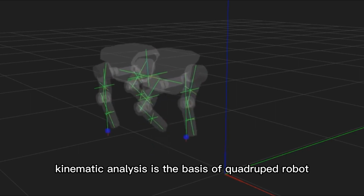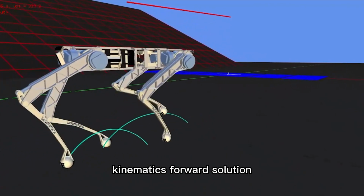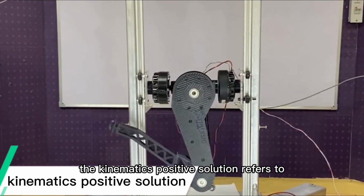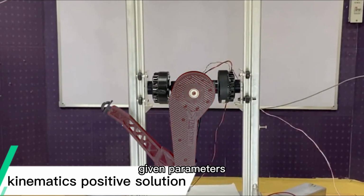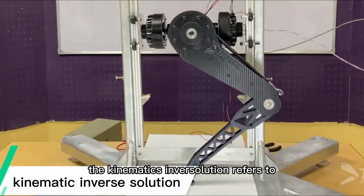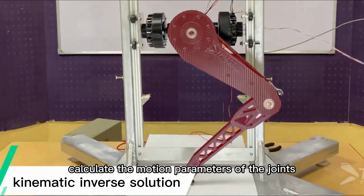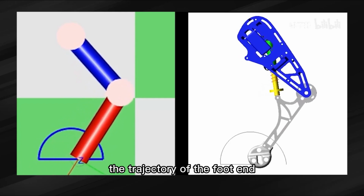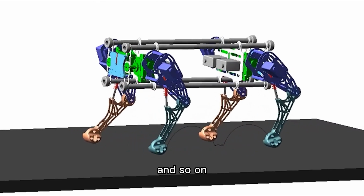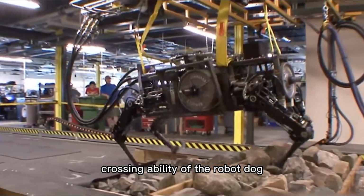Kinematic analysis is the basis of quadruped robot, which is divided into kinematics forward solution and kinematics inverse solution. The kinematics positive solution refers to given parameters to solve the position and attitude of the end. The kinematics inverse solution refers to given position and attitude, calculate the motion parameters of the joints. The trajectory of the foot end affects the accuracy of the robot dog steps and the stability of walking, and so on. At the same time, it affects the obstacle crossing ability of the robot dog.